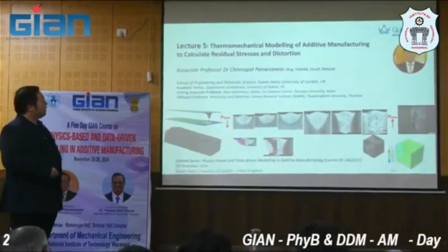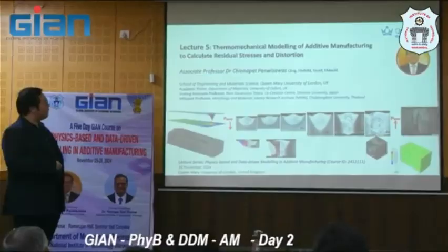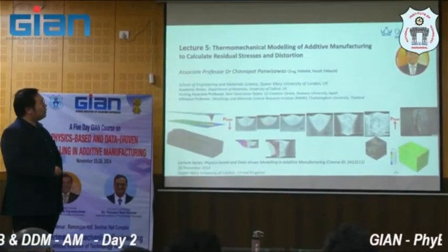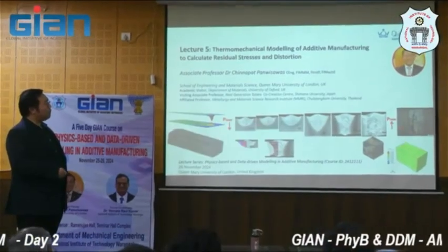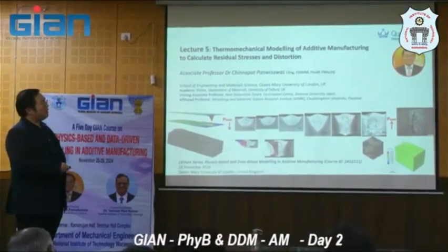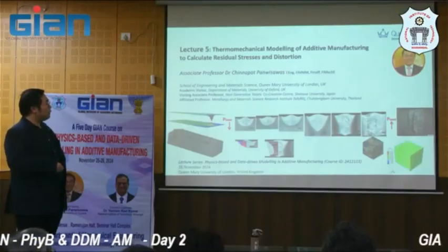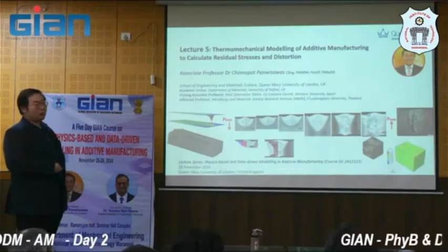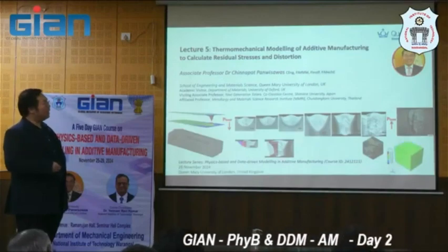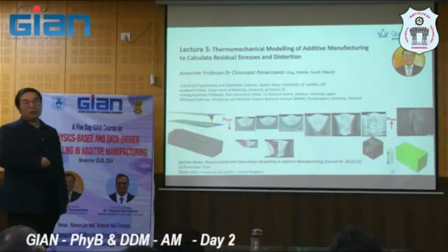In this slide you will see that the laser power, lower and higher, will change completely from the conduction mode to the keyhole mode, for example, and that changes the microstructure as well, from equiaxed to columnar grains. From this snapshot, this picture may already summarize what happened here, and what the consequence of this microstructure is to property. This is what we are going to talk about.